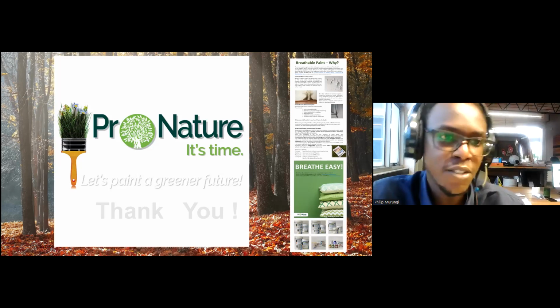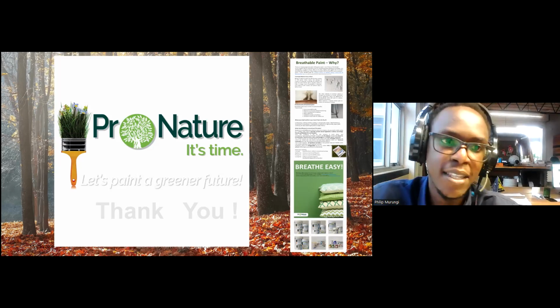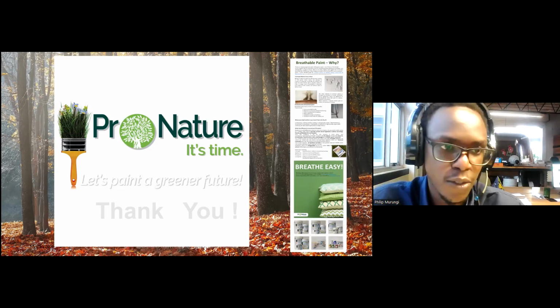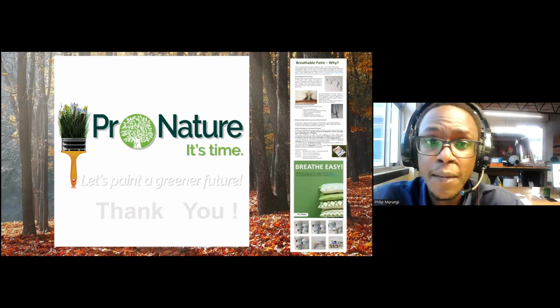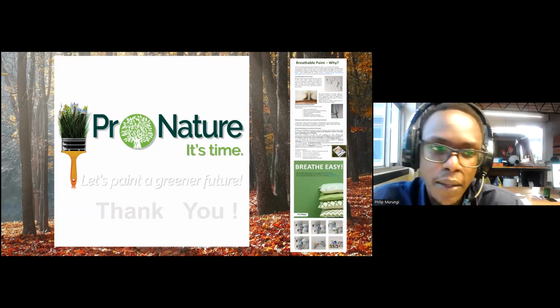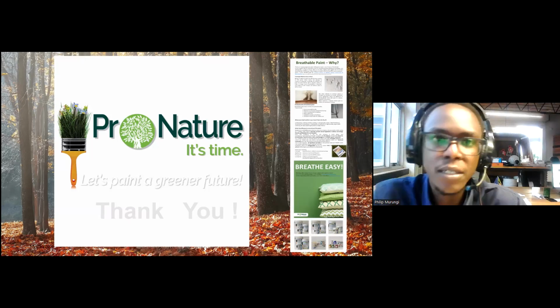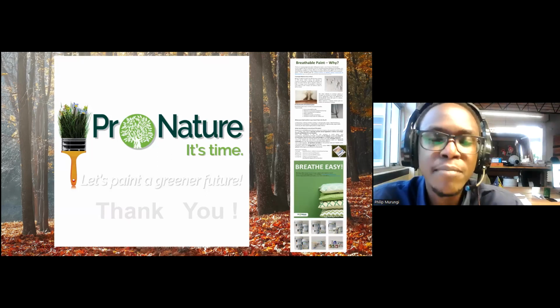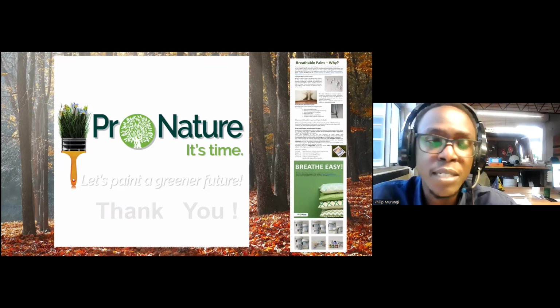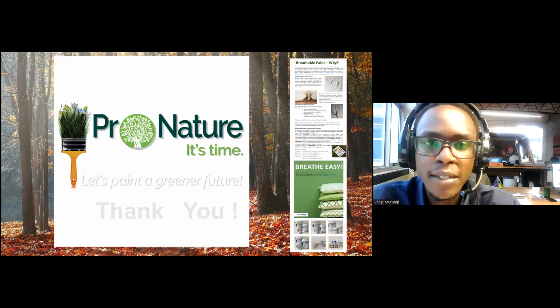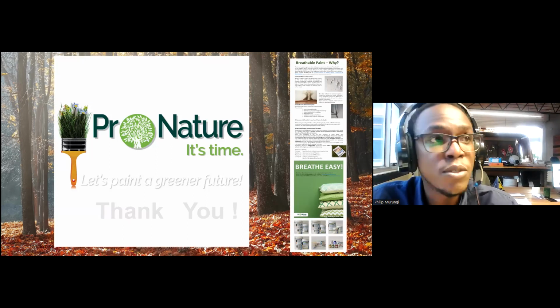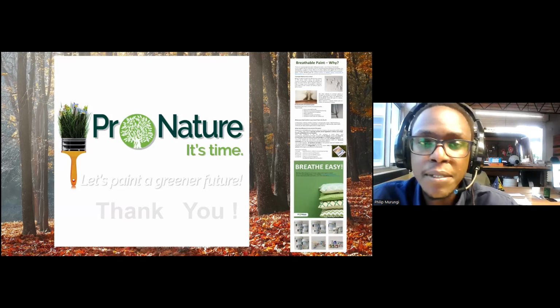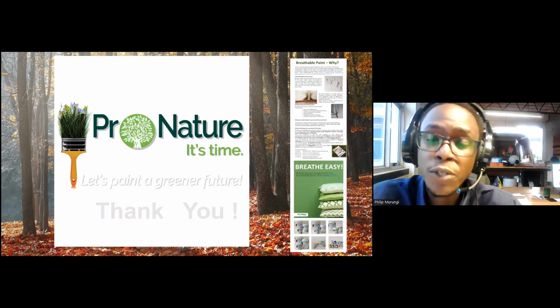Okay, interesting question. He said termites, he said moisture and heat. So I'll tackle termites and moisture together. So termites and all insects are basically looking for food. There is a minimum moisture content at which timber becomes food. It's about between 14 and 20%. And anything below that, you're basically safe. So the first thing we do, of course, is to season the timber and keep the moisture content below 14%.